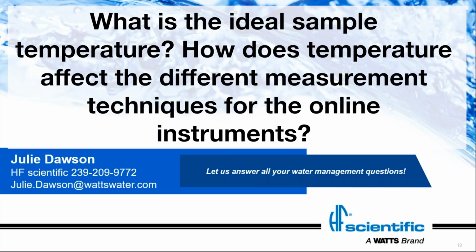For the ion selective electrode, we want to make sure that we are at the same temperature as our calibration solutions are. So the sample and the calibration solutions, as well as the ionic strength adjuster, all need to be in close proximity. So generally we would say room temperature for this, but because we know we need to make that measurement within 15 minutes of bringing it inside, we may have to use an ice bath or a heater depending on where we're located in the country and the temperatures of our samples to make sure that we're measuring that correctly.